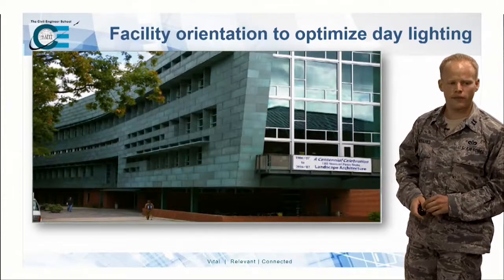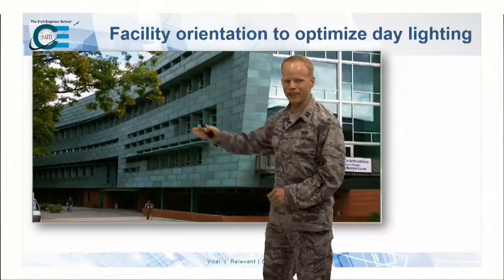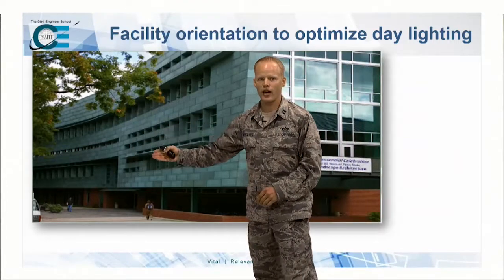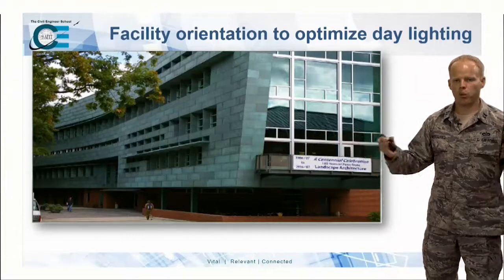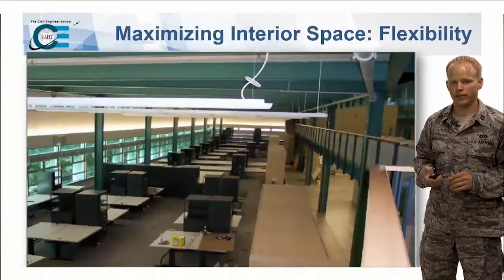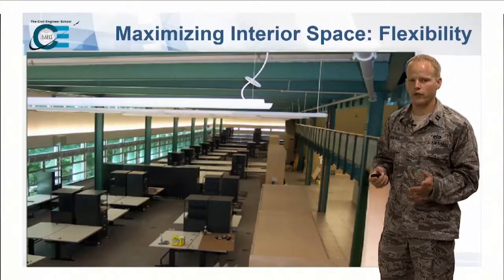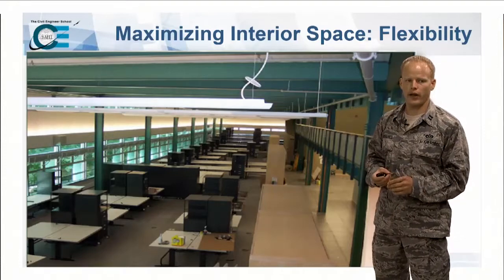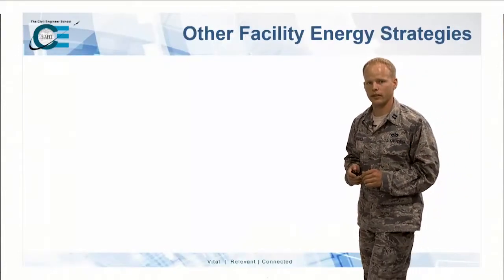Facility orientation, you want to orient it so you can optimize daylighting. Over here, can't get much daylighting, a lot of shade. Over here, you can. So how you orient your building will play into your daylighting strategy. And then optimizing your space. One is flexible, but two, if you can have an open space, you can better distribute daylighting through that space.